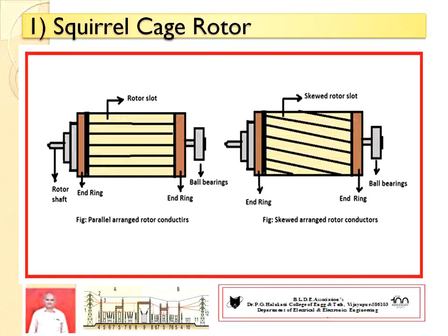If the rotor conductors are arranged in parallel, such an arrangement poses certain problems. The motor may refuse to start. Magnetic locking between stator teeth and rotor teeth. The motor produces more magnetic hum, more noise may be produced, and it produces a pulsating torque. All these are problems. So, to overcome these problems, the rotor bars have been arranged in skewed position as shown